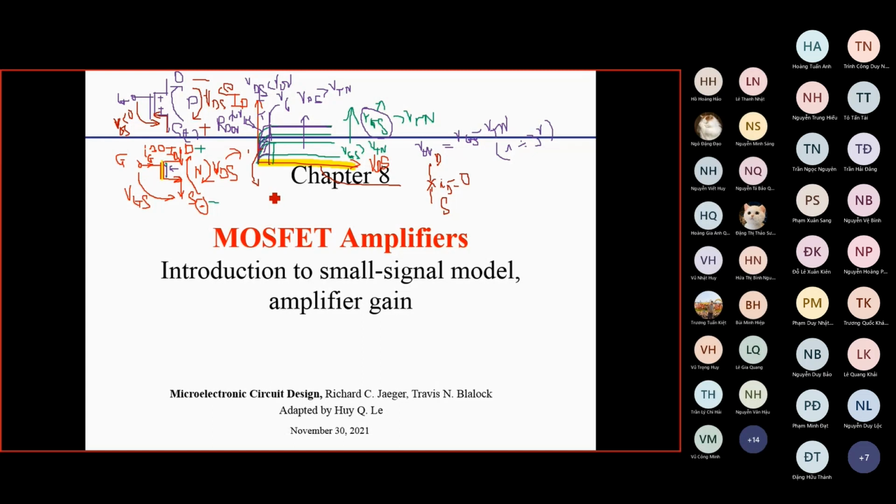In the triode mode, the voltage drop between the drain and the source is small here. So the transistor can be used as a closed switch, but the resistance RD between the drain and the source is quite large here. In this case, we cannot omit it. We count it as RDS on. So the transistor can behave as a switch that is turned on, but it's not an ideal switch because there is a resistance between the two contacts of the switch.